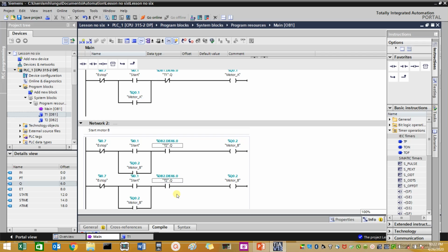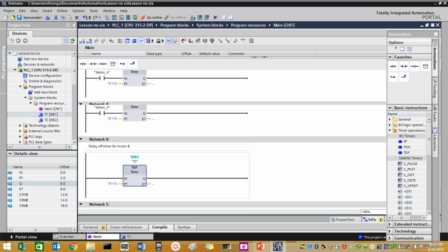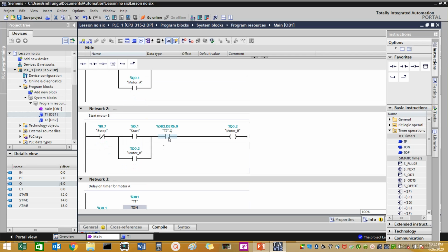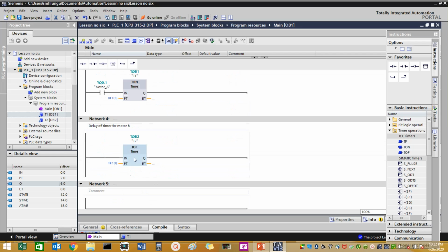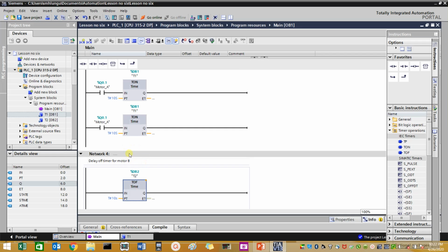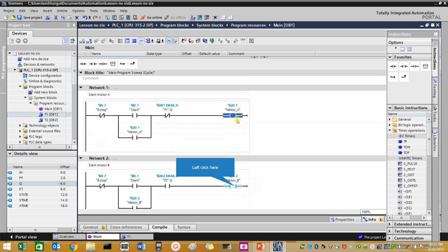All right, now let's go back and see there. That delay off timer, we've just pulled up a normally open contact and connected it in there, because we know that as soon as the relay gets power, or this function block is energized, this will close immediately, making sure that this motor and that motor start rotating at the same time.